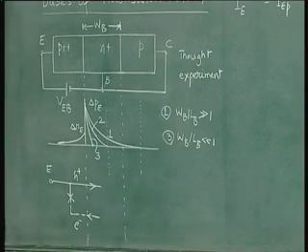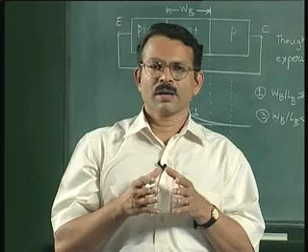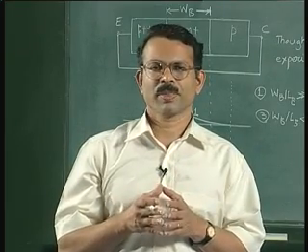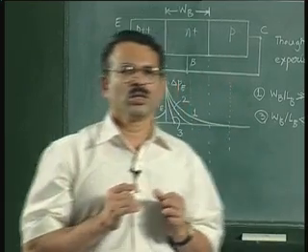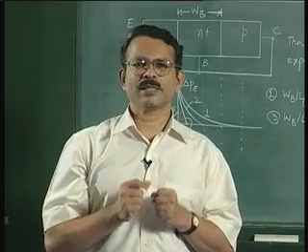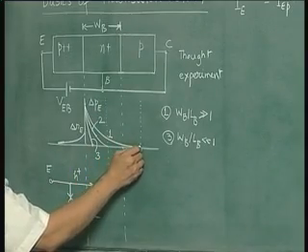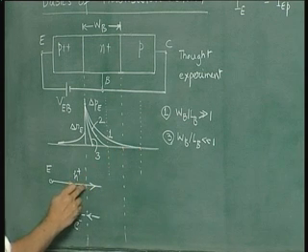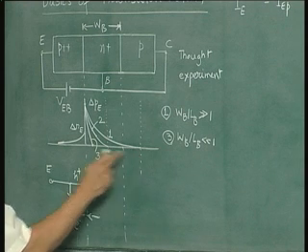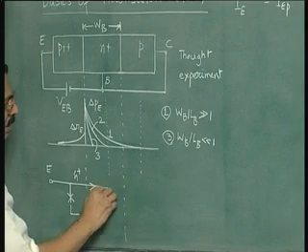Now we know from p-n junction theory that the current in a bipolar transistor is because of diffusion in the neutral regions and diffusion of minority carriers, which means that the current depends on the gradient of the excess carrier concentration. So the diffusion current of holes here is 0, which means all the holes which have been injected into the n plus region or base have all recombined for this particular situation. So for case 1, the picture will be all these holes recombine.